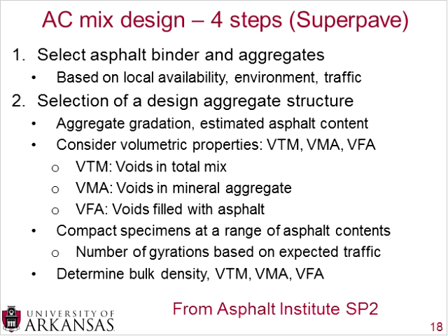And then your gradation is often determined by what application you're putting it on. If it's a larger gradation, those are sometimes on the lower levels of pavements, down there in the structure. If it's a finer gradation, that'll provide a quieter, smoother surface, so that's often put on the higher layers of pavements or the surface courses. But there are a lot of details that go into selecting your gradation and your estimated asphalt content.